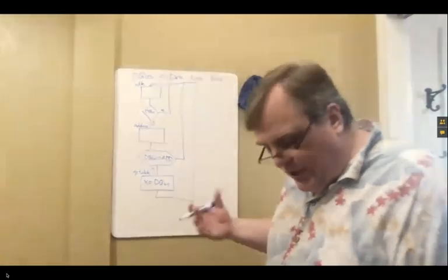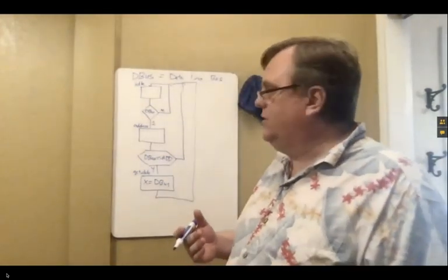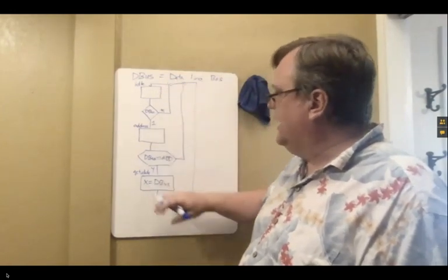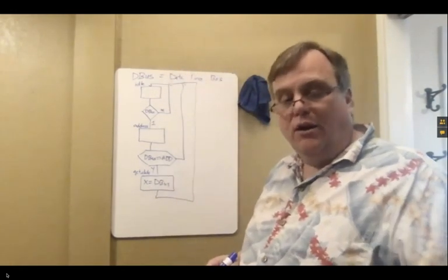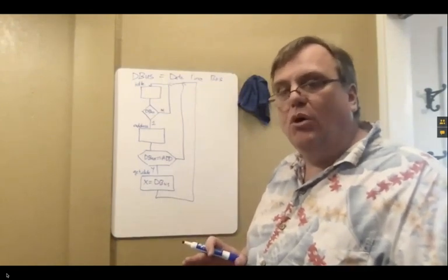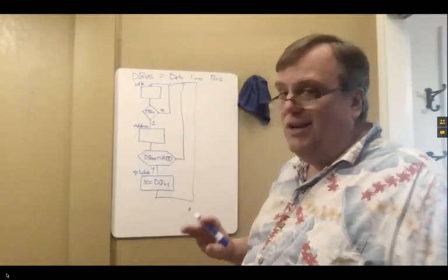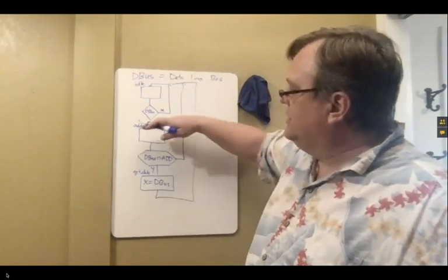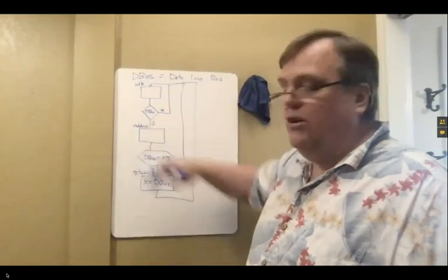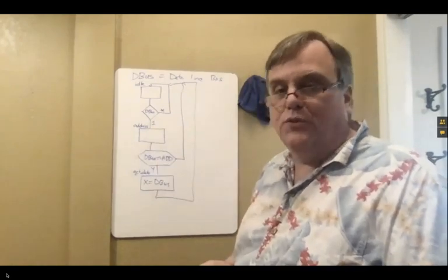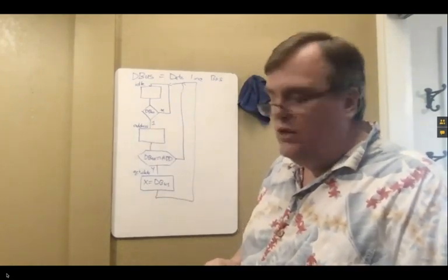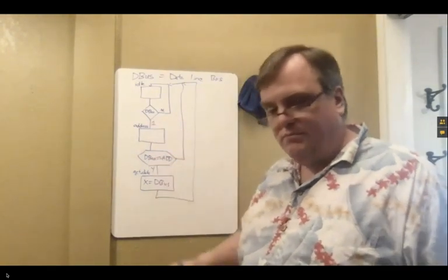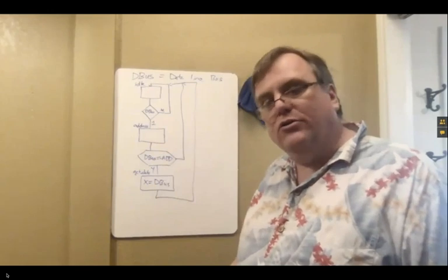So somebody could easily tell me that piece of thing. There's kind of three states to it: a wait state, check your address, get your data, return to wait state. This is not too different than most of the buses. It's a little simpler, but it's not a lot simpler than buses you'll see on a computer. For instance, this address and data aspect here is exactly what takes place on the memory bus inside your computer. These have become very wide buses. These buses are usually 64 bits wide or so.